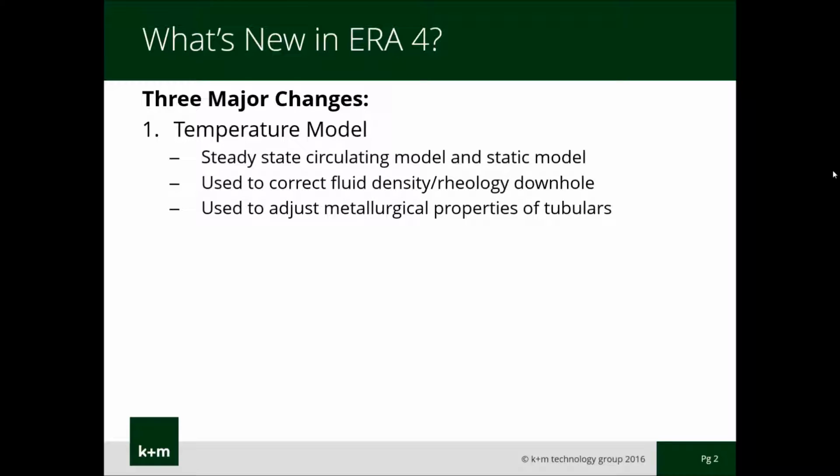The temperature model can be used to predict downhole and flowline temperatures. The thermal engine also allows us to adjust fluid density and fluid rheology to downhole conditions. Drill string and casing metallurgical properties can also be corrected for thermal effects thanks to the thermal model.